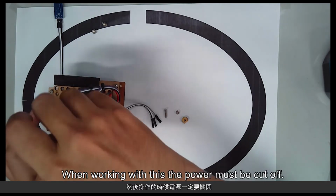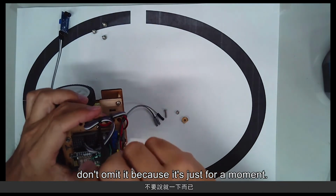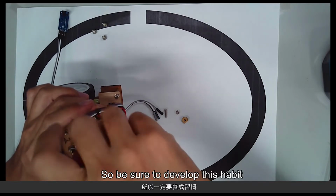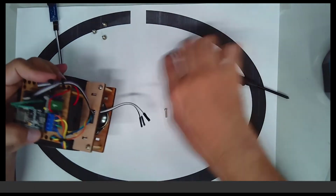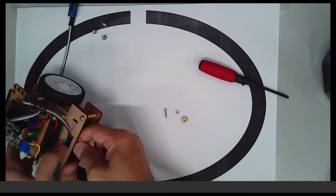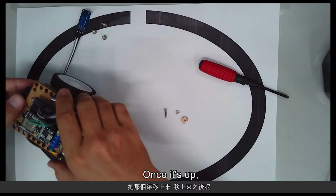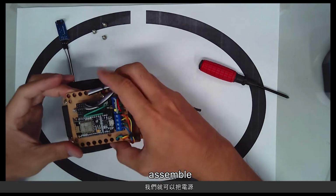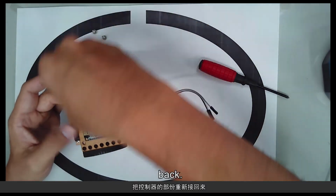When working with this, the power must be cut off. You should develop this habit. Don't skip it just because it's only for a moment. If you're careless for one moment, you'll short circuit and burn it out. So be sure to develop this habit of cutting off the power whenever you're working with wiring. We'll pass the wire through and move it up. Once it's up, you can assemble the controller board back.